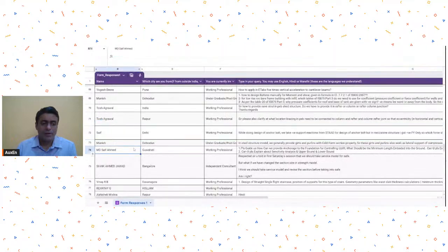You can just put a base plate, have a column on top of it, and load will get transferred through bearing between the base plate and RCC pedestal. But still, of course, we will provide some minimum number of anchor bolts.